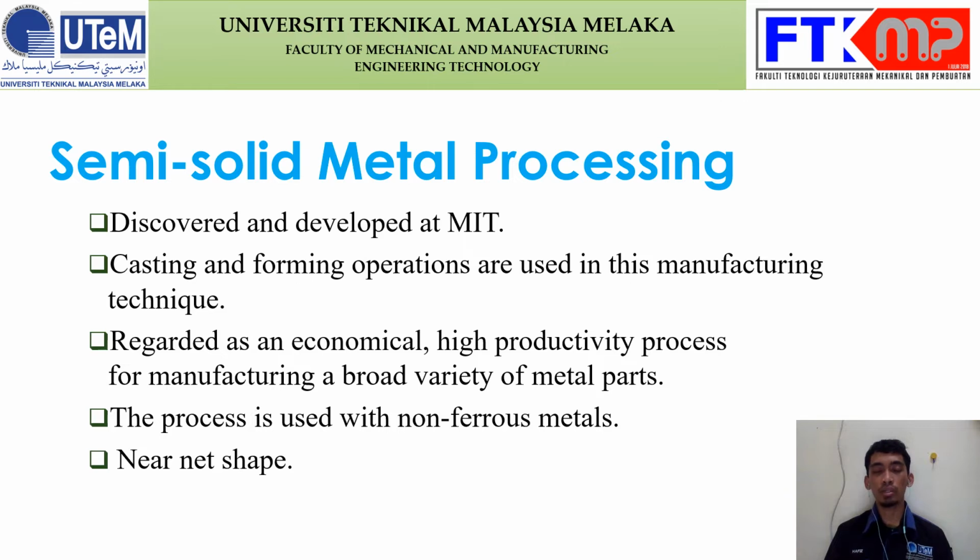Casting and forming operations are used in this manufacturing technique, regarded as an economical, high productivity process for manufacturing many types of metal parts. This is used with non-ferrous metals such as magnesium, aluminum, or copper. Semi-solid metal processing is near net shape.